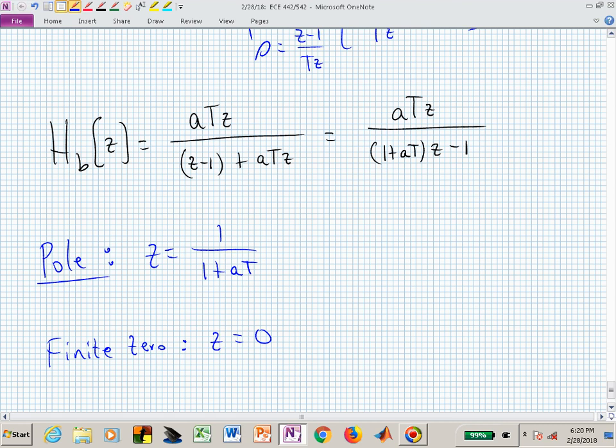How many steps? If you now had z, that's our mode. If we had 0 raised to the n, it's going to vanish in one time step, isn't it? That's called a deadbeat response. If we had a pole at the origin, it's lickety-split fast, right? So now we have a 0 at the origin, so that's a fast 0, and that's kind of consistent with not having one in the analog case.